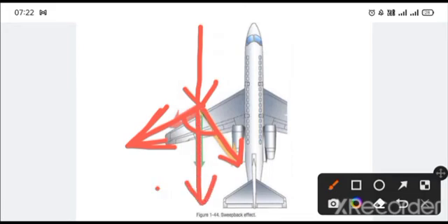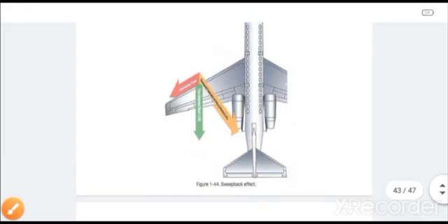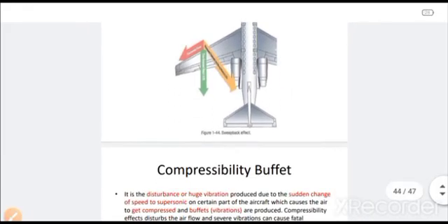Okay, so this particular relative movement is the only part necessary to produce the shock wave. But as it is suffering some sort of hindrance when it strikes the leading edge and gets diverted into two directions, the energy is decreased. So the rest of the air flowing over the surface does not have that amount of energy or speed to produce the shock wave. So that's the reason this type of structure has been put in the wing configuration.